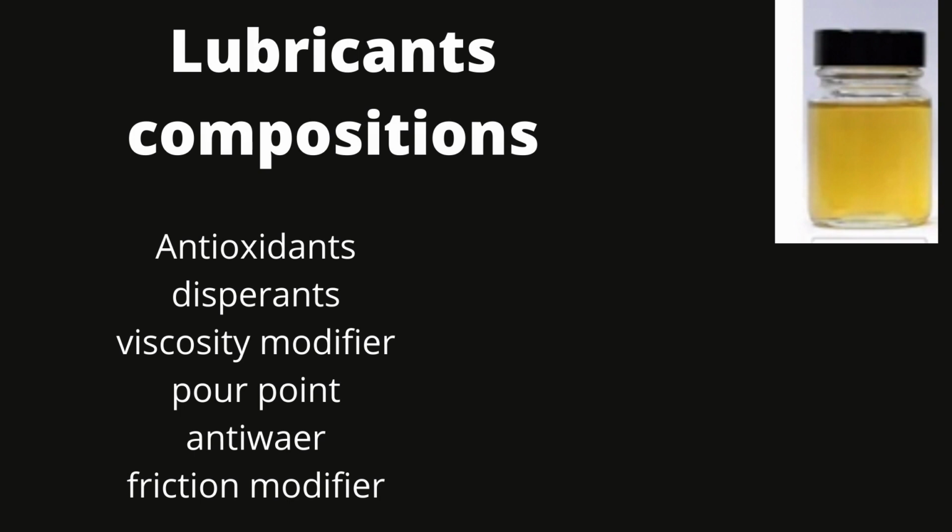Lubricant composition. Not all oils have all the lubricant compositions. Some oil will have some compositions like antioxidant, dispersant, viscosity modifier, pour point enhancer, anti-wear additives, friction modifier.